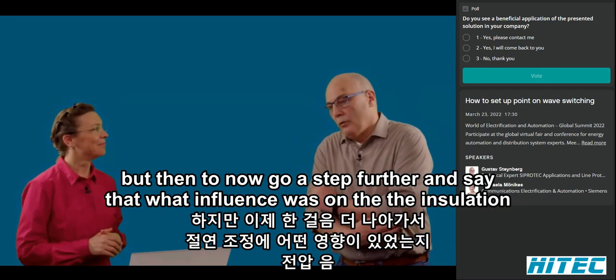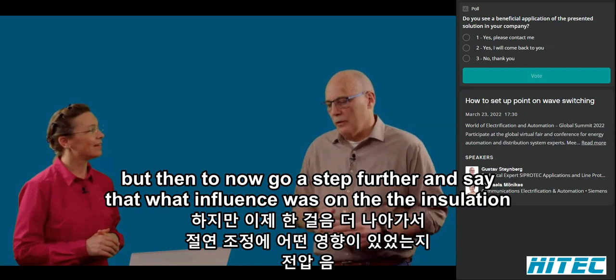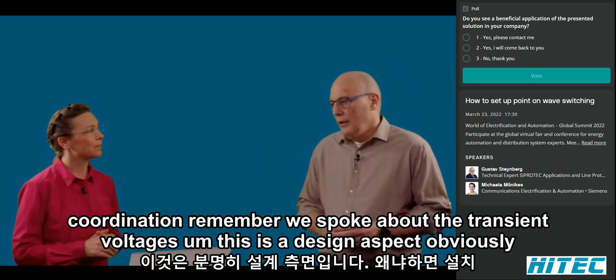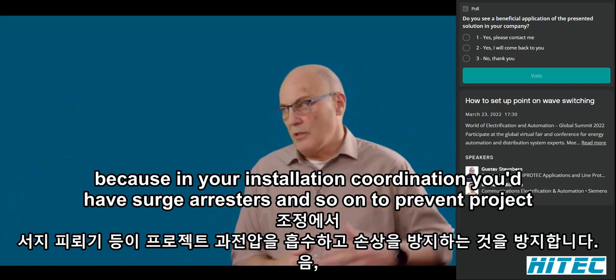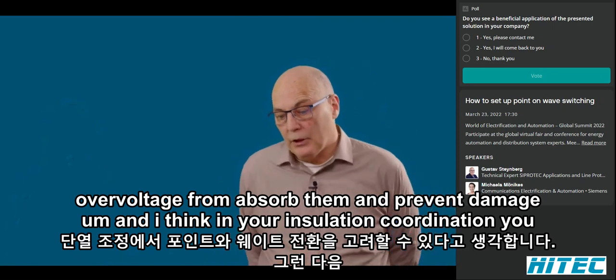But then to go a step further and say what its influence was on the insulation coordination. Remember, we spoke about the transient voltages. This is a design aspect, obviously, because in your insulation coordination you'd have surge arresters and so on to absorb transient overvoltage and prevent damage.